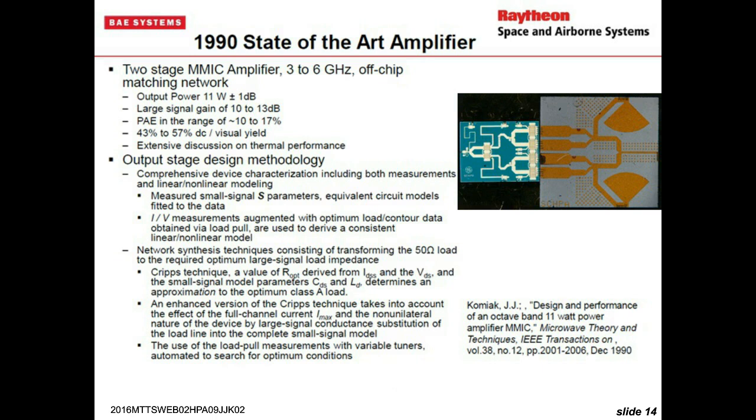But also, in most amplifiers that you use, like a common source or common emitter type device, if it's a bipolar, your device is not unilateral. And so changes in your output matching network change your input or interstage matching network. And that makes it much trickier to get the design centered, especially over bandwidth.